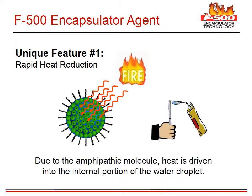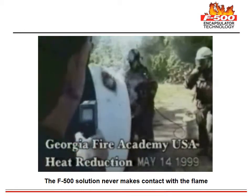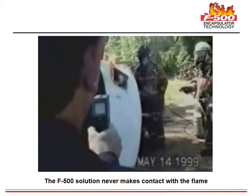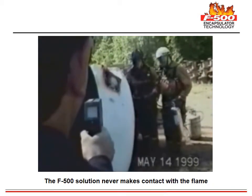A very unique feature of F500 encapsulator agent is heat reduction. As the amphipathic molecules form around water droplets, they efficiently draw heat from the fire into each water drop. This demonstration at the Georgia Fire Academy shows the cooling capabilities of F500. A propane torch is used on the opposite side of the steel plate to heat the paint to its auto-ignition temperature. A laser pyrometer is used to monitor the temperature, which peaks at about 1300 degrees Fahrenheit.